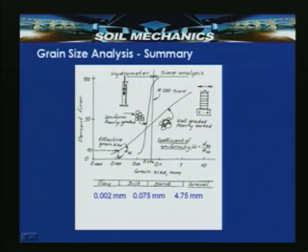Uniformly graded means the particles are of equivalent size, and you can see that this steeper curve represents a uniform, poorly graded soil, and this one represents a well graded soil because the finer particles are filling the voids within the large particle sizes. So, this is a well graded soil type.